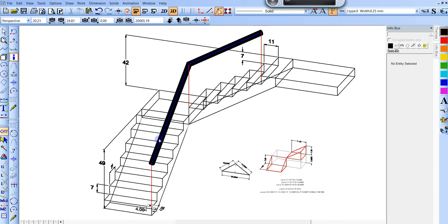All right, welcome. In this video, I'm going to talk briefly about a single miter handrail. You'll see it on round handrails quite often. The one angle in between those two pieces is called the dihedral angle. It's what you would cut if it was laying flat on the table. So if you were to put this in a chop saw with this piece straight, you could cut that angle and then flip it around, and without rotating it, it would be on the right angle.